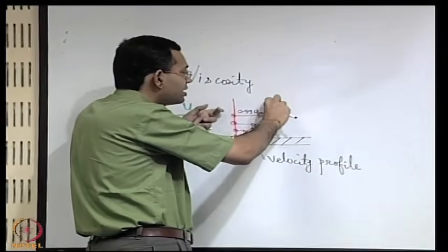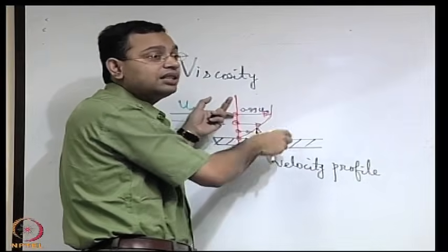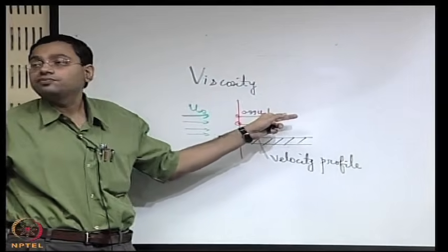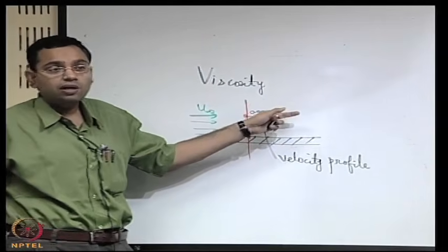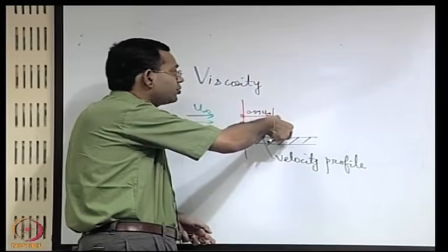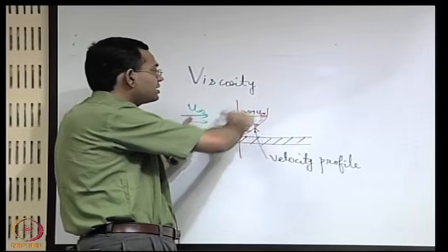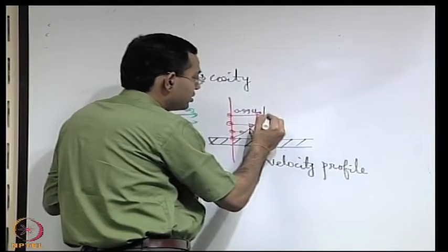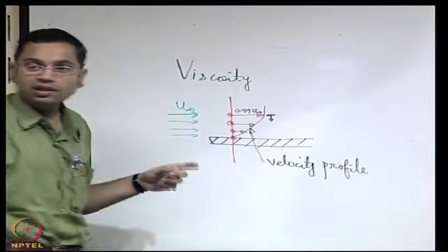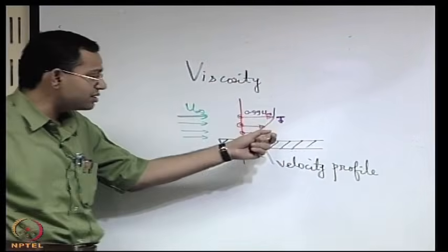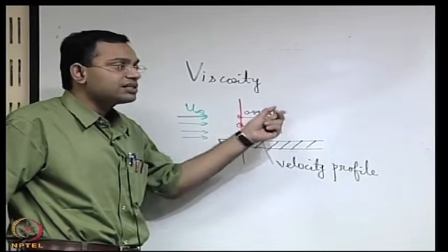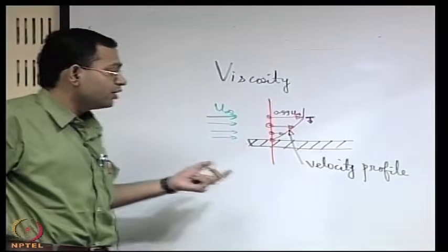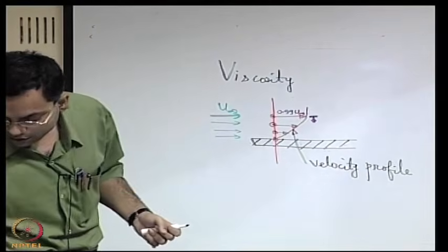That means beyond this the fluid does not directly feel the effect of the wall at all. That does not mean that the fluid does not have viscosity, it has viscosity, but the momentum disturbance could propagate only up to this much. So, we may demarcate the physical behavior, one below this threshold location and another above this one. Below this the fluid adjusts itself with the momentum disturbance, above this it does not feel the momentum disturbance. Let us consider a second cross section.